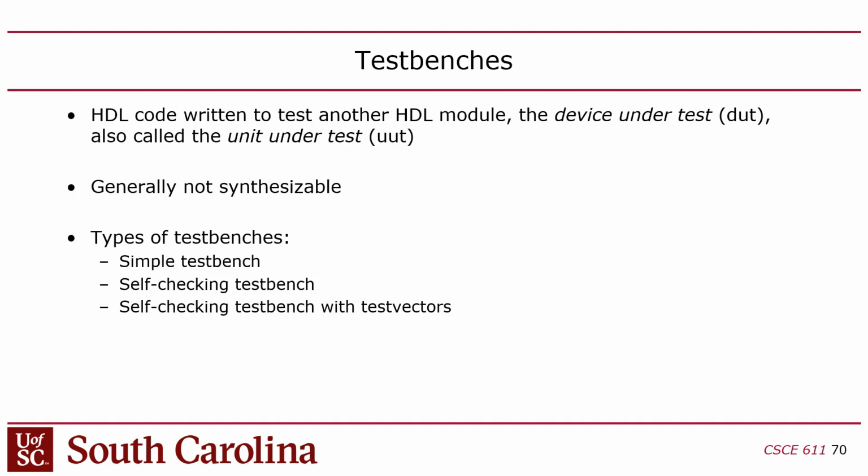It's not really practical to do that. So the way you're supposed to do it, especially for more complex designs, is to create a test bench. A test bench is just a SystemVerilog wrapper that goes around something you're going to test. And the wrapper does two things. One, it sets the inputs, so you don't have to write Tcl commands in ModelSim. You can just have the wrapper set the input stimulus for you, the test inputs.